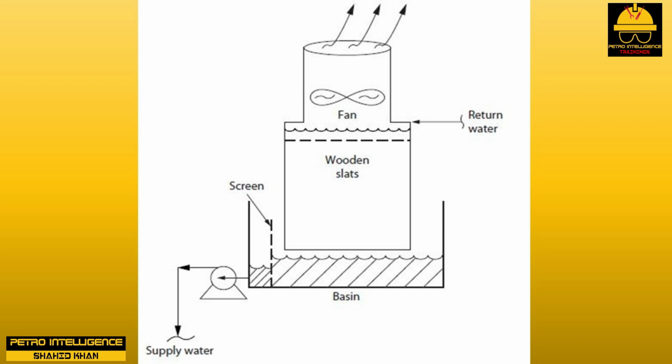Why? Because he was running on the flat portion of the cooling water supply pump performance curve. Was there any reward for his efforts? Yes. The amperage load on the cooling water pump motor was reduced from 60 to 50 amps, an improvement that was of no interest to manager.